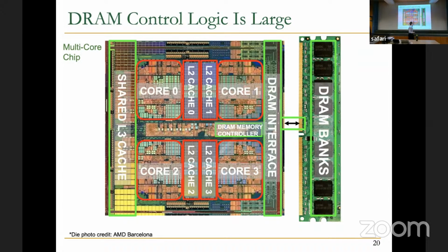That's why the memory controller had its separate chip, because that would be a logic chip that you could customize for logic, and you could customize DRAM for DRAM. And then that chip got integrated into the CPU or accelerator chips, which makes sense because it's also a logic chip, right? So that's the history of things. But today, with emerging technologies, if you have 3D stacked logic and memory, it may make sense to reconsider that historical design decision.